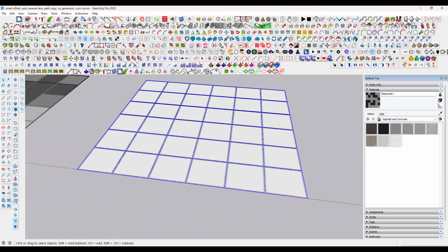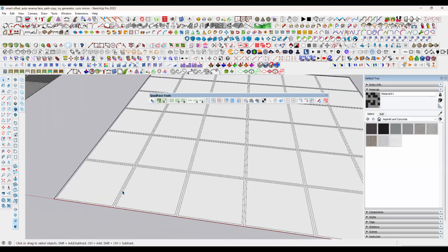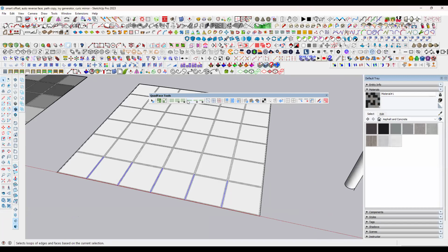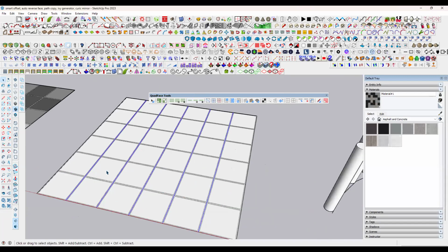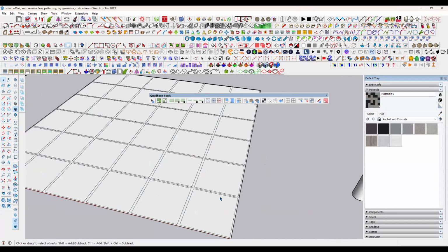The technique is we have a tool named the quad face tool. In the quad face tool, I am selecting only one series of lines here. See, I am selecting only these 4 lines. Then immediately I am going to use this tool. The tool name is select loops. So with the help of this quad face tool, see what I can do. I can select easily. Once I click only one line, the complete series of lines is going to be selected at a time, then I can click on delete.